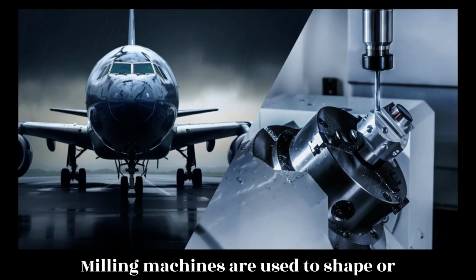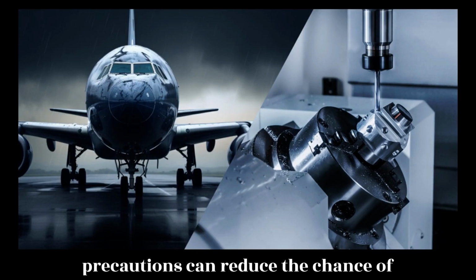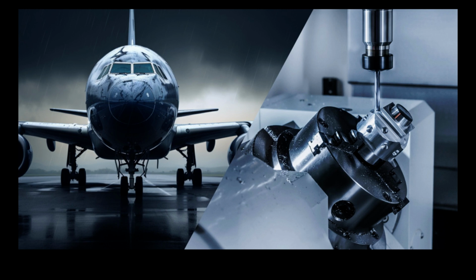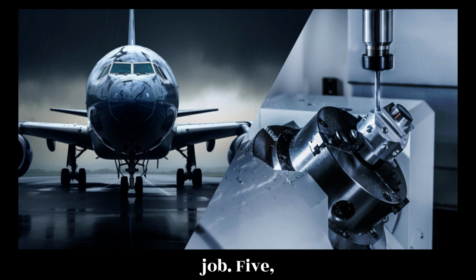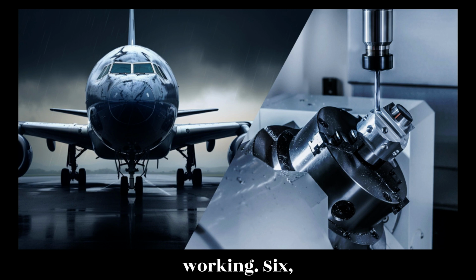Milling machines are used to shape or dress, cut gear teeth, slots, or keyways, and similar work. The following precautions can reduce the chance of injury. 1. Wear eye protection. 2. Clean the work bed prior to work. 3. Secure the work to the bed to prevent movement during milling. 4. Select the proper tools for the job. 5. Do not change the feed speed while working. 6. Lower the table before moving under or away from the work. 7. Ensure all clamps and bolts are passable under the arbor.